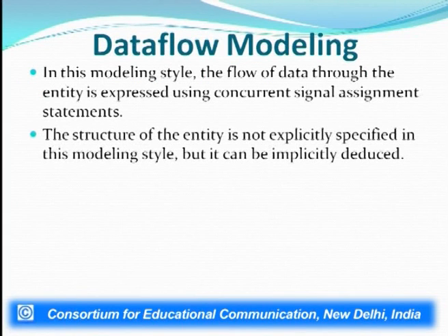Now, moving on to the second type of modeling, which is the data flow modeling. As I mentioned earlier, it is just indicating how the data is flowing between the input and output signals or any intermediate signals or variables, if any. So, in this style of modeling, the flow of data through the entity is expressed using concurrent signal assignment statements. The main difference between data flow and structural is that the statements will be concurrent.